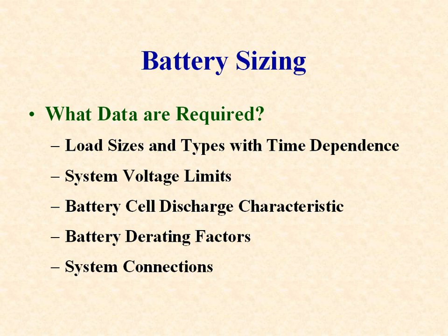Battery derating factors for age, temperature, and design margin must also be specified. The system connections are usually defined when building a system model, but are not required for a battery sizing study.